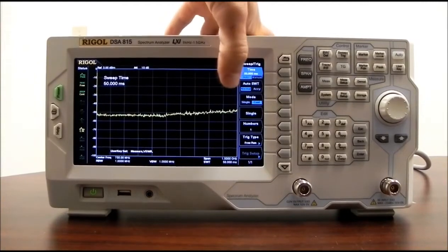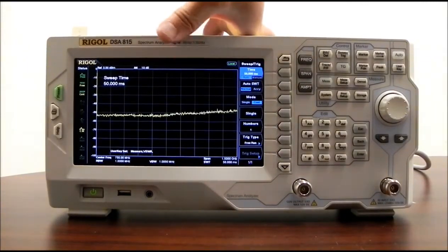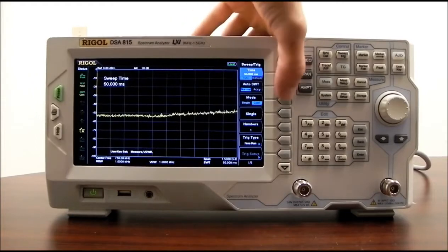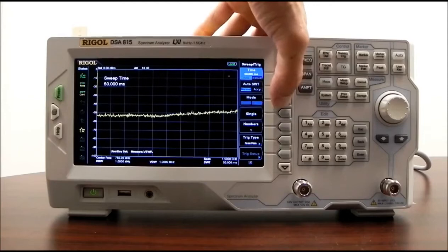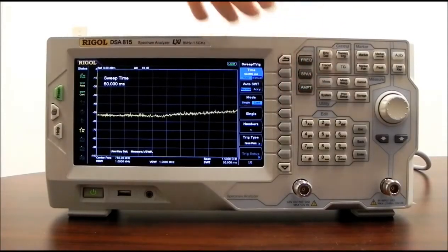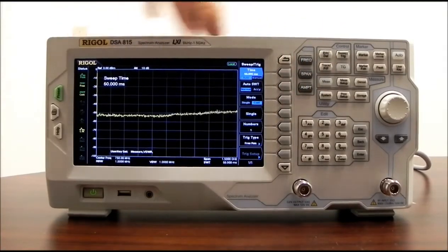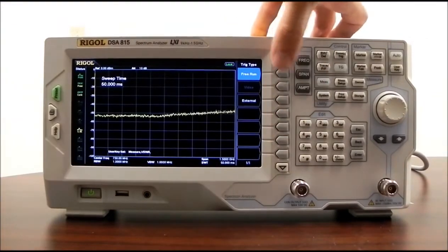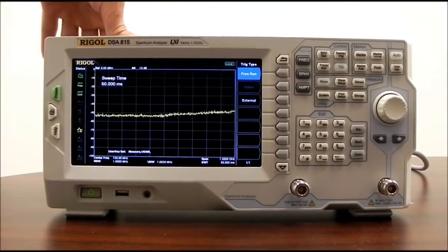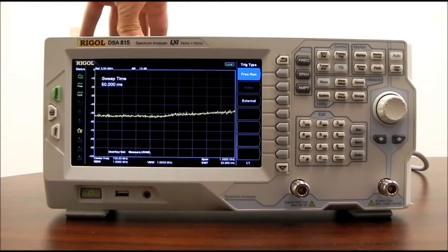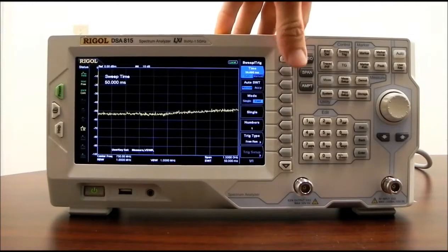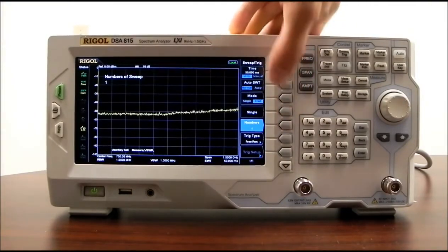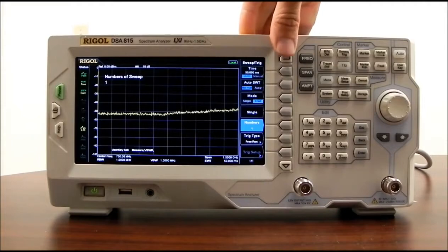We have auto sweep time. We want to keep that normal, or we can go to accuracy mode. Then for mode, we can go continuous or single, and with single we can just press single trigger if we wanted to capture just one image. We also have the ability to do an internal trigger, which is going to be free run, but we can also do external. There is a BNC connector on the back, a TTL level signal, so if you wanted to trigger it in an automated way in order to capture images, you could do that as well. You can set the number of scans per trigger using the numbers key.